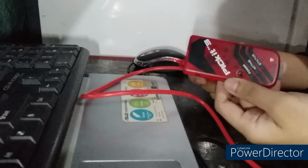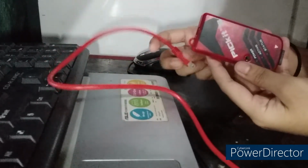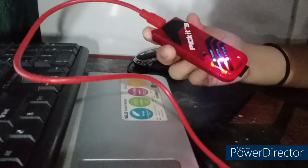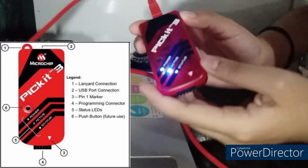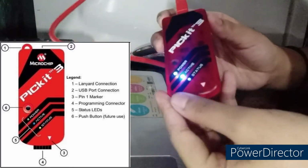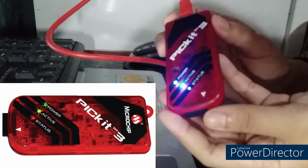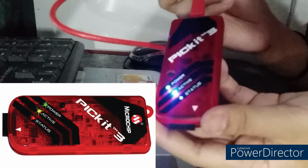And now we have here our Pickit3. So we will be connecting it to our MPLAB through our USB cable here. So let's connect it. So as you can see, on the screen, I will show you the legends for the basic parts of our Pickit3, and I will show you the meaning of each of the colors here on our Pickit3. So for our green, it indicates our power for Pickit3. The power is supplied to the Pickit3 via the USB port, as you can see here, the red wire here.